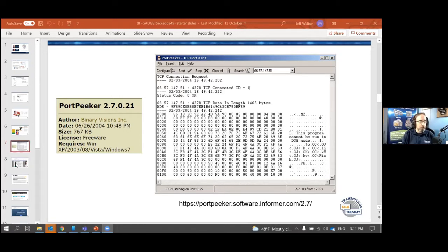So Port Peeker was one of the ones. The cool thing about Port Peeker is, if for example you look at the IP address of your Nautel transmitter, port 7005, you'll be able to see if the RDS data is coming into it. And in the comments over to the right, you can actually read the RDS data. That's kind of useful because one of the biggest challenges I've run into with troubleshooting RDS is figuring out, is the data even getting to the transmitter from the automation system? So having something like that will let you know. That's a big troubleshooting tool.